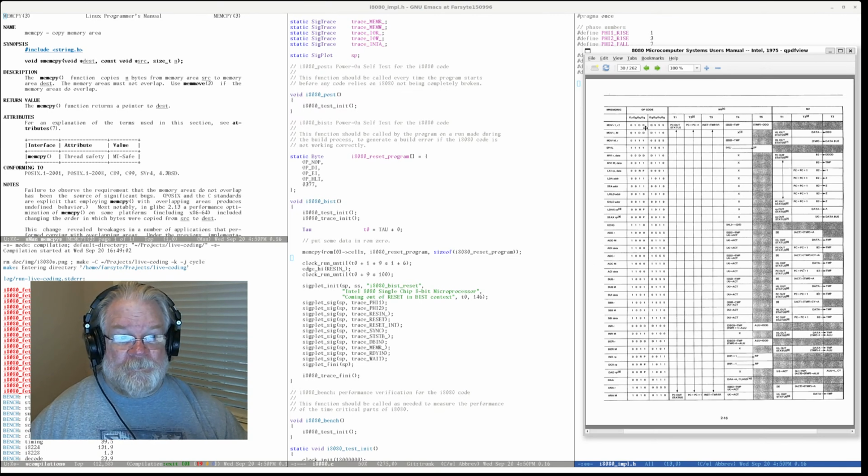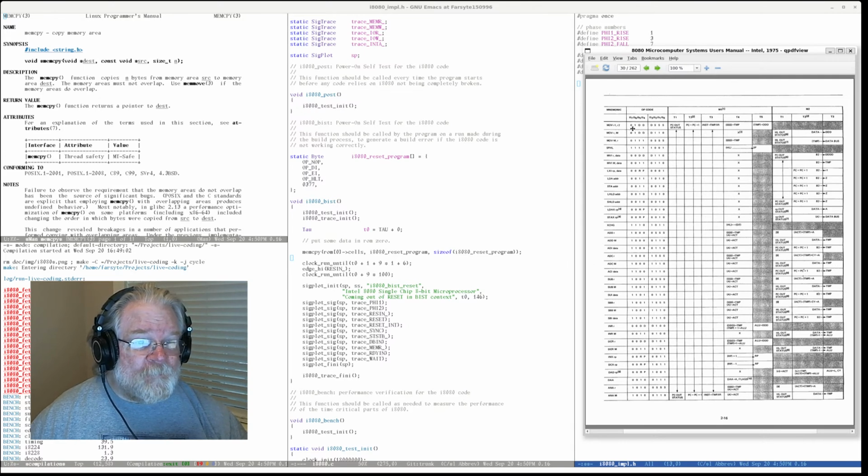Well, you don't move directly to and from memory on the x86, on the 8080. So the encodings for, well, we've got move RM and move MR. We do have those. So you can load and store internal registers from where HL points, but you can't move from memory to memory. That would be a no-op because you'd be reading from a memory cell and writing back to the memory cell.